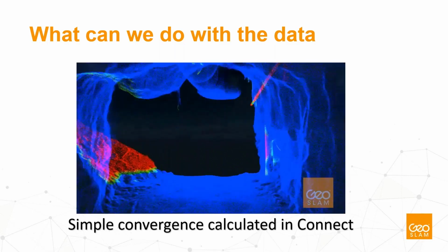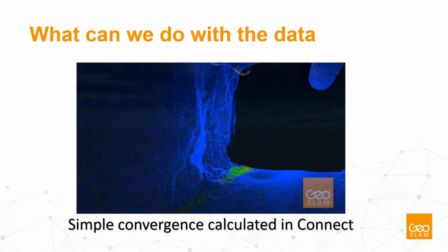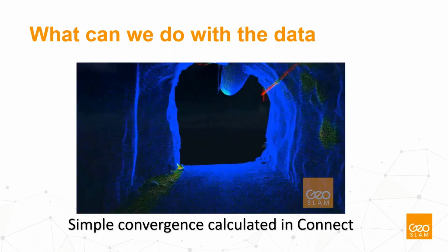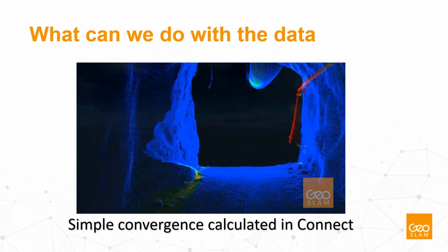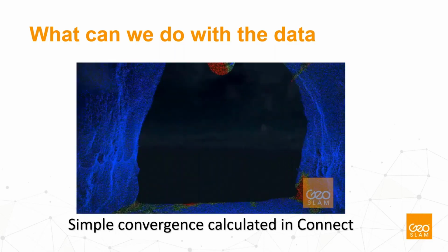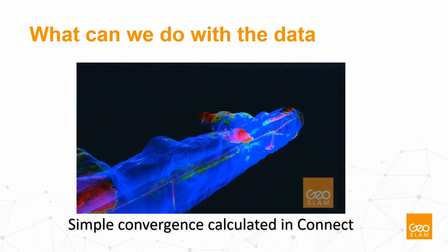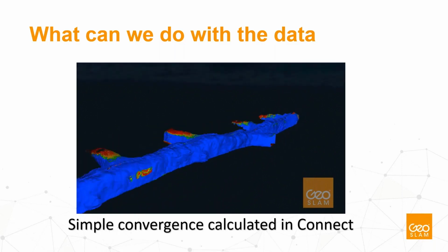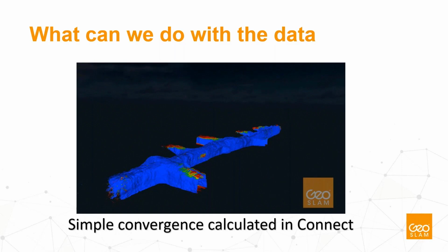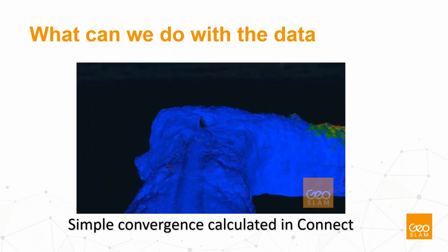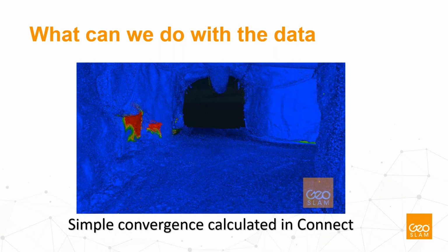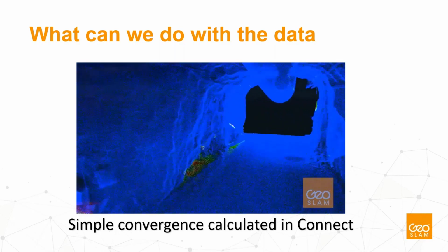But I find it interesting how it's consistently picking up on the pipe on the right-hand side. We're having a bit of convergence in some places. This is enough of a deliverable to a geotech to go down and investigate the area. There's obviously going to be changes in the vent bag, but it's just a nice data example of some change we see in some headers. Most of the time it's not down to geology. Most of the time somebody's backed their loader truck into the wrong piece of equipment that causes vent bags to collapse, or it's just a stockpile underground being shifted. So again, it's a nice clean point cloud that we're delivering here, georeferenced, and the red shows any changes.